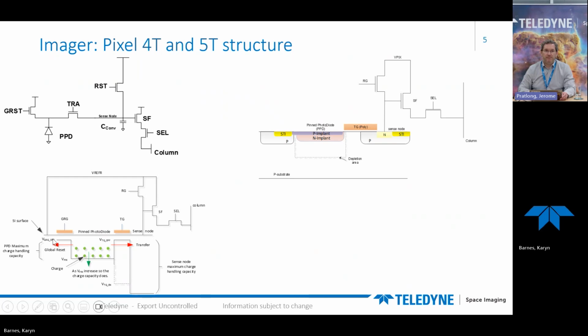The fifth transistor that can act as a global shutter function, but also as an anti-blooming, will have an applied DC voltage on the gate. By modulating this voltage, we can create a path for overflow, making sure that extra charge captured by the photodiode is not spilled out in the neighbor pixels.